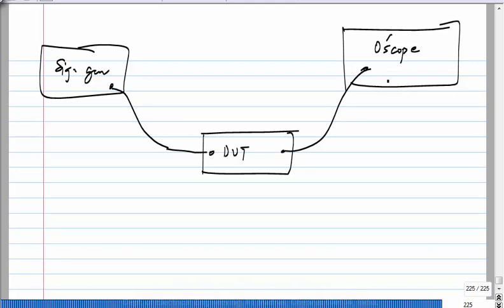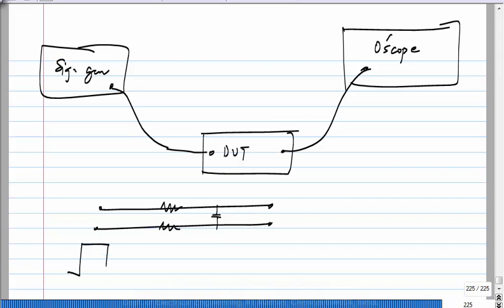Now, these wires are not perfect. Let us say you think of a pair of wires, they will at least have some resistance and some capacitance. So, the wire by itself is some system whose transfer function is not 1. But at least we can reasonably rely on it to be linear. That is, if you do not pass very high currents or apply very high voltages, it will be linear. Now, imagine what would happen if you apply a square wave to this? What will you get here?